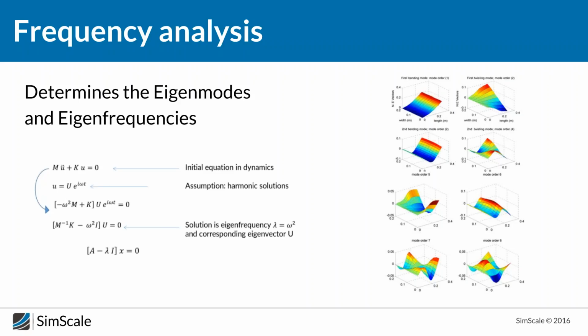But if you're interested in what it provides, what you get back for the structure, it is simply this: if your structure had no bearing, it would be just like it is. The natural eigenfrequencies would be the frequencies where your structure would do those natural eigenmode movements, which you can see illustrated on the right for a very simple geometry. So this is simply a plate. But it also provides much information for more hands-on industrial applications and problems, but we will see that in a second.